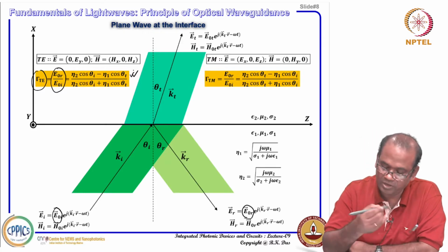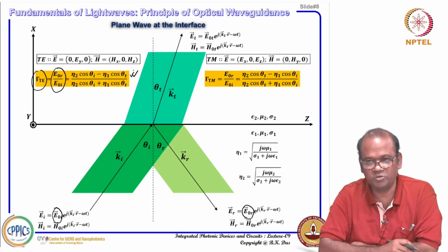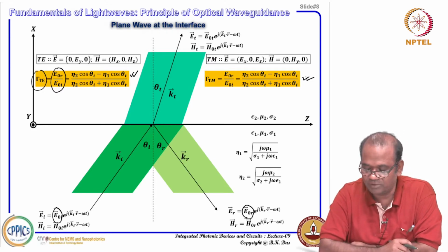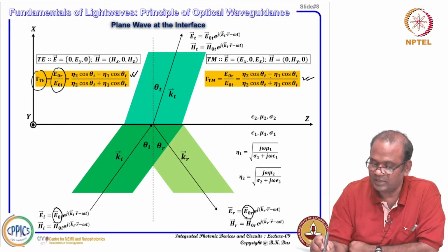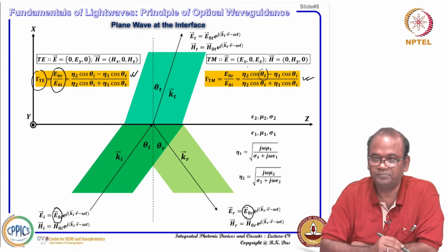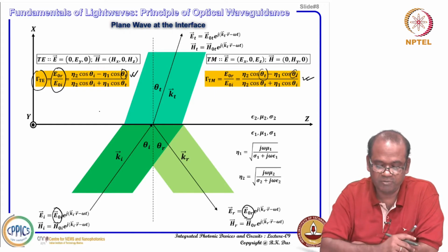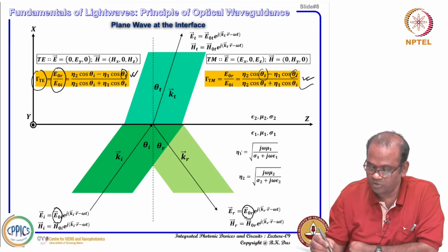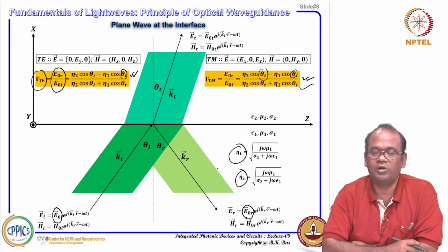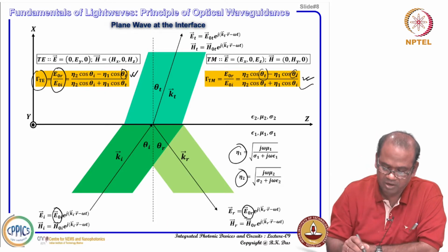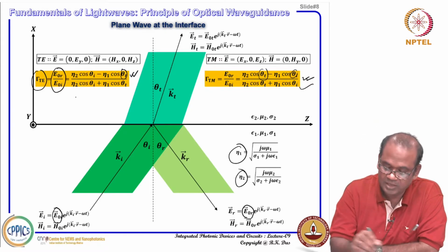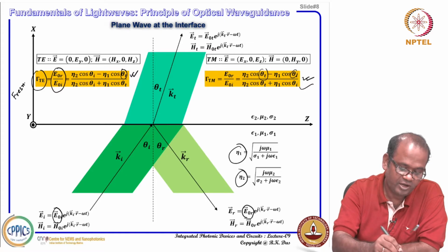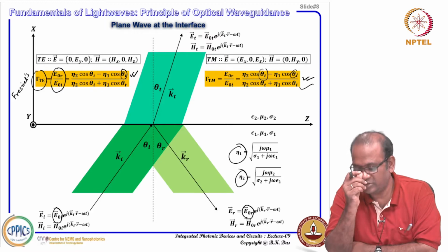Similarly, utilizing the boundary condition, in a few steps you can do this, and in any electromagnetic textbook you can find it. So, for TM polarization I can also find this. If you compare, they are almost identical looking; the only thing is that theta i and theta t are interchanged. In the first term theta i was there, and here the first term is theta t. Otherwise, the numerator and denominator are the same, with plus and minus only. So, the reflection coefficients for TE and TM polarization can be derived in terms of the intrinsic impedances of the two media, eta 1 and eta 2, and they are of course theta i dependent. These were first derived using boundary conditions by Fresnel, so they are called Fresnel's equations, Fresnel's law of reflection.